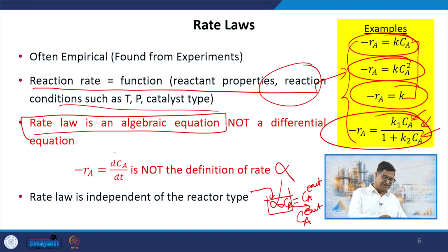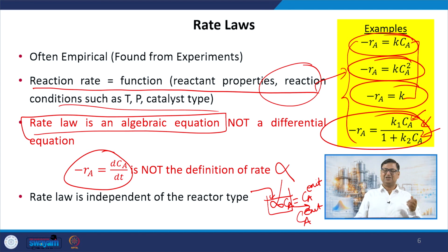So, if I use this expression, it will wrongly suggest that Ra is equal to 0, that means no reaction is taking place, which is nothing further from the truth. The fact that we have a CSTR, that is a reactor, means reaction must happen. The reason this happened is because there are inflows and outflows, and that should have been considered, right.